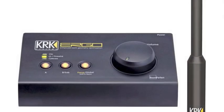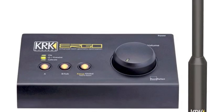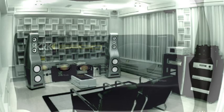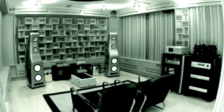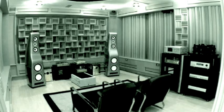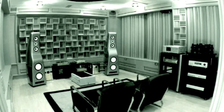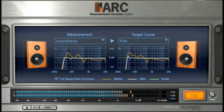Room correction systems aim to improve the frequency response of a control room using equalization. Room correction has been applied for many years, although room correction systems aim to do most of the process automatically and more accurately. In short, room correction is based on measuring the frequency response of a room and then compensating dips and peaks using equalization.